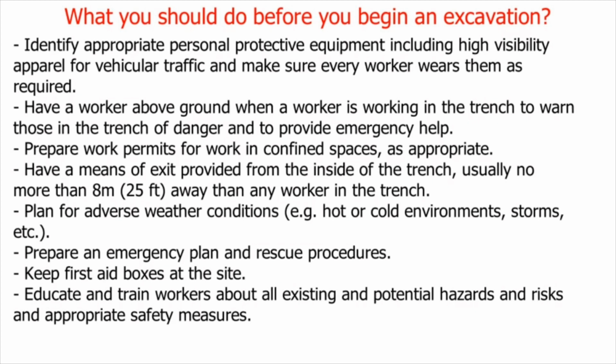Have a means of exit provided from the inside of the trench, usually no more than 8 meters, 25 feet, away from any worker in the trench. Plan for adverse weather conditions, for example hot or cold environments, storms, etc. Prepare an emergency plan and rescue procedures. Keep first aid boxes at the site. Educate and train workers about all existing and potential hazards and risks and appropriate safety measures.